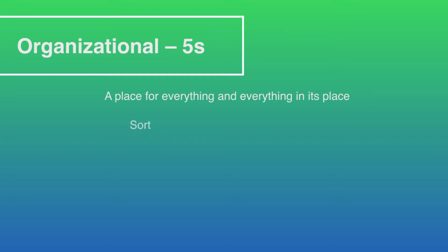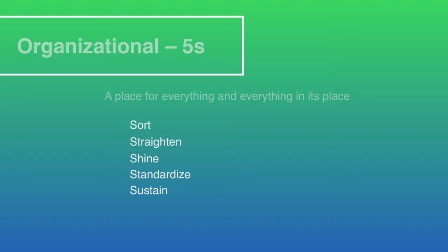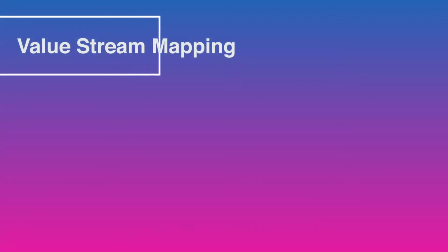Organizational robustness is achieved through the implementation of a 5S approach. This involves sort, straighten, shine, standardize, sustain. First, the clutter and unused equipment is removed as part of sort. Then the actual equipment to be used in the new layout is planned and arranged. Next, the facility equipment is made to shine. This includes being clean. This includes operating as it was designed. Once the above three elements have been addressed, the goal is to fully standardize the operation, so each piece of equipment operates equivalently according to its specification and design features.